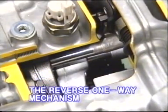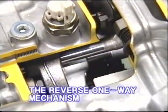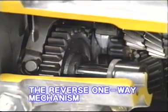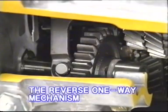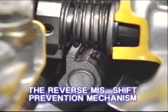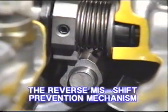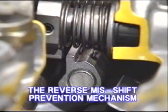The reverse one-way mechanism controls the reverse idler gear to move only when the transmission is shifted into reverse. The reverse miss-shift prevention mechanism prevents accidental shifting directly into the reverse gear from fifth gear while the vehicle is in motion.